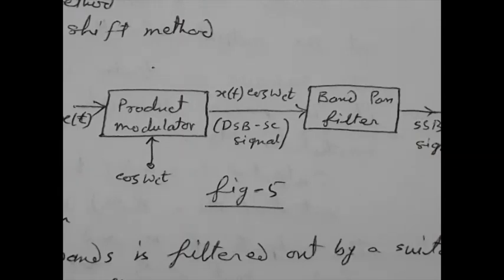However, the system is not useful for video communication, where the baseband signal starts from DC. That's a major drawback of this system. And another restriction of the frequency discrimination method is the baseband signal must be appropriately related to the carrier frequency.